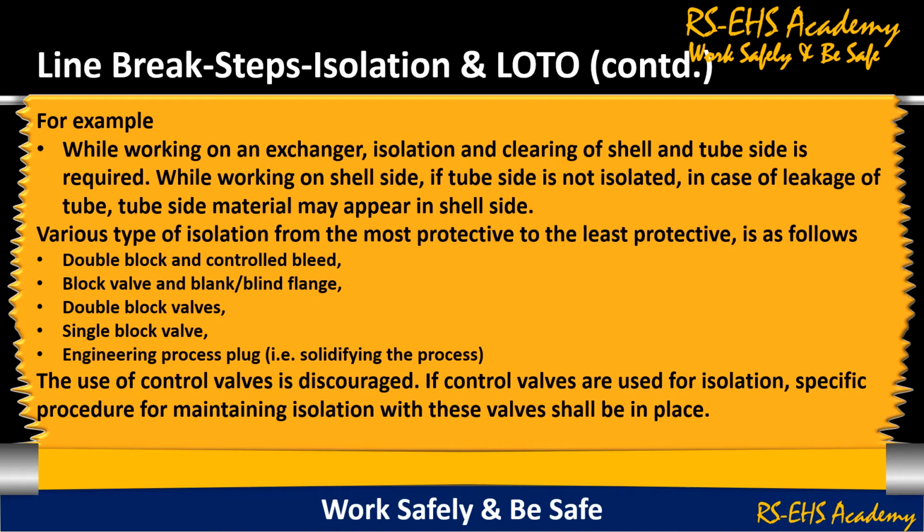Double block and control bleed. Block valve and blank or blind flange. Double block valves. Single block valves. Engineering process plug, that is solidifying the process. The use of control valves is discouraged. If control valves are used for isolation, a specific procedure for maintaining isolation with these valves shall be in place.